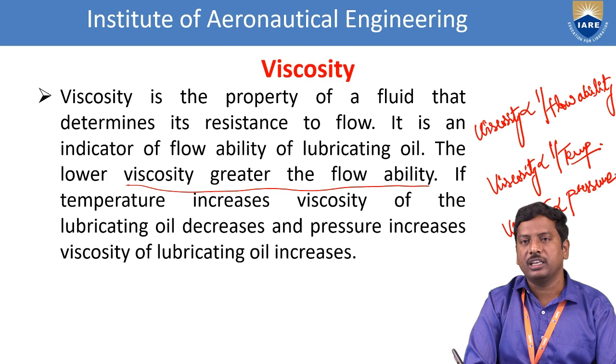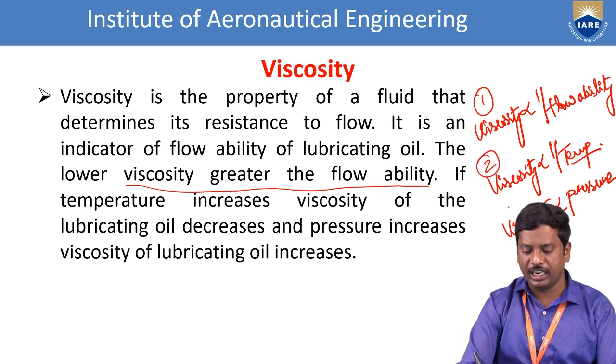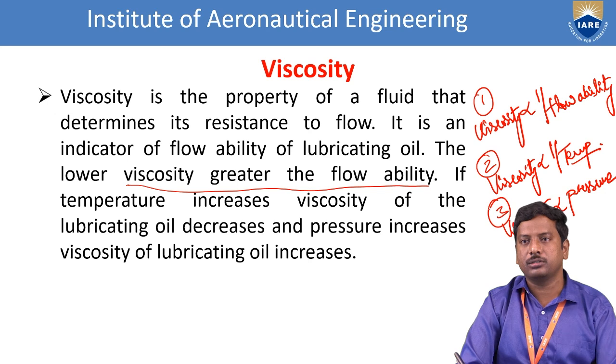So this is about the viscosity of the lubricating oil with respect to different conditions. Viscosity is inversely proportional to flow ability, inversely proportional to temperature, and directly proportional to pressure. Viscosity is nothing but a resistance to flow, that means the dragging force between the two layers.